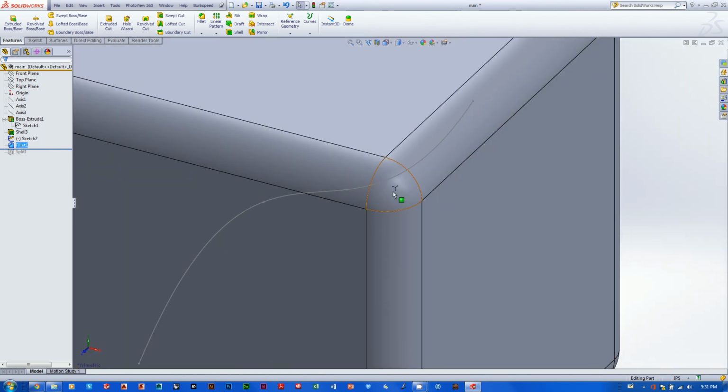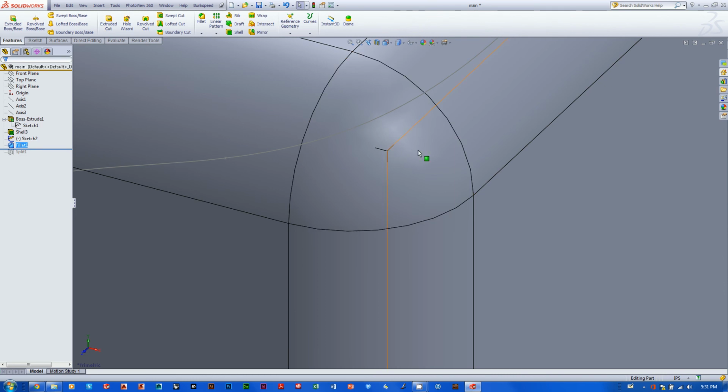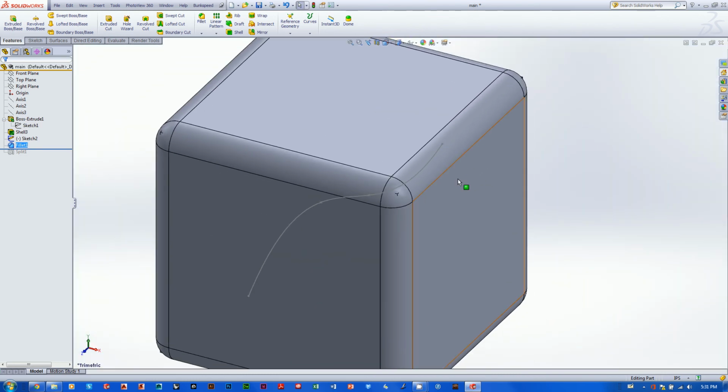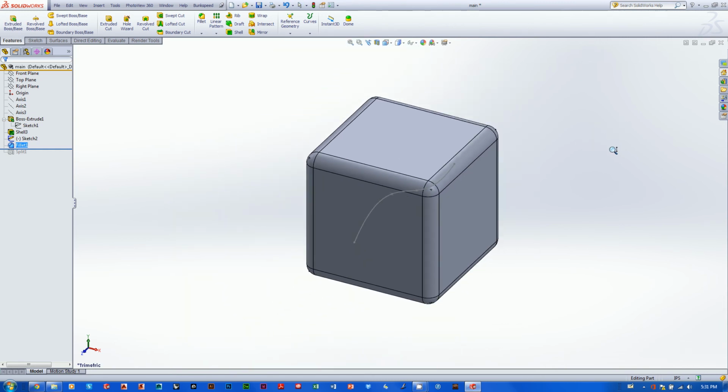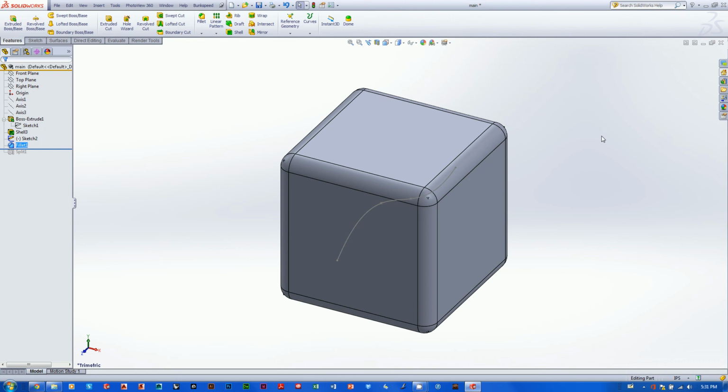Look at this. What's this here? It looks like the shell that we created earlier and the fillets together is causing the interior wall thickness to poke through where that fillet has trimmed off the exterior surface. Well, there's a solution for that, and this is it.